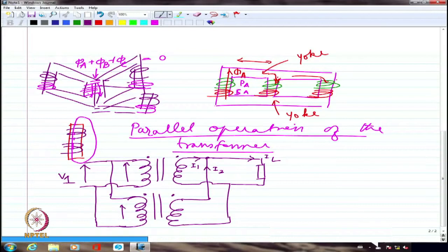Definitely, no doubt that if I install one 50 kVA transformer, just one single unit of 50 kVA transformer, that will be less costly at the time of installation as compared to 20 plus 20 plus 10. Very clearly, because everything has an individual core, everything has individual parts. So you are going to definitely increase the overall cost during the installation.